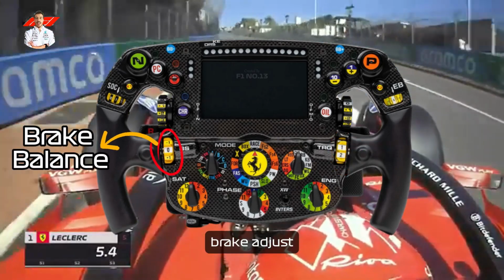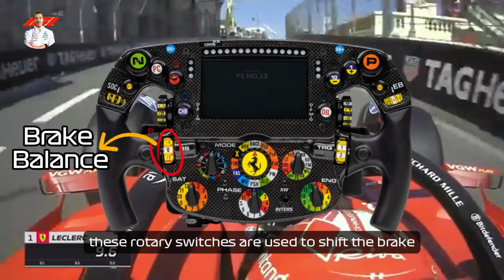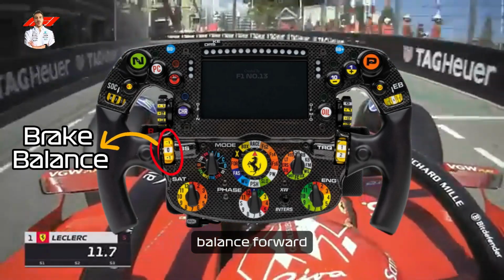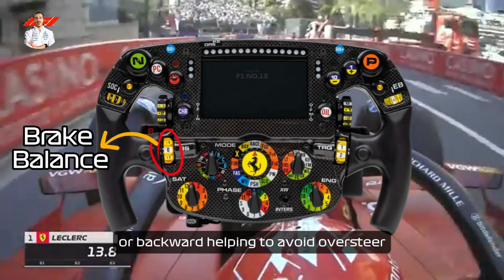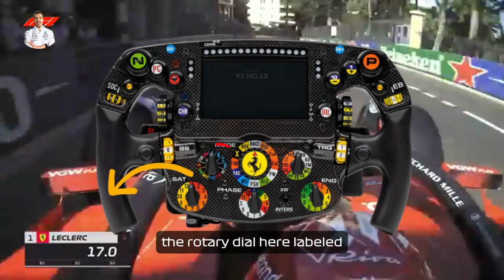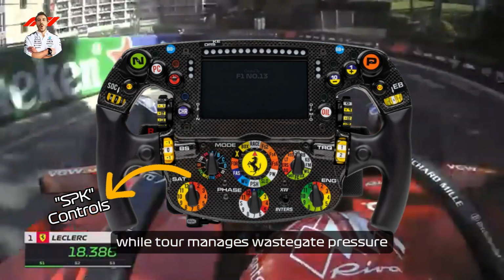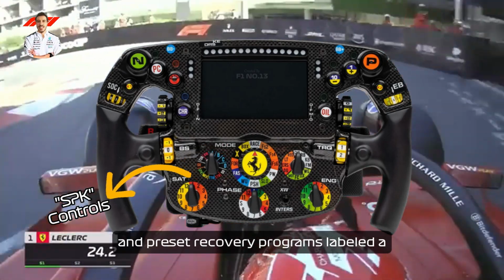Brake balance, adjust the braking force applied to the front or rear brakes. These rotary switches are used to shift the brake balance forward or backward, helping to avoid oversteer, rear instability, and brake lockups. The rotary dial here labeled SPK controls spark ignition, while the other manages wastegate pressure and preset recovery programs